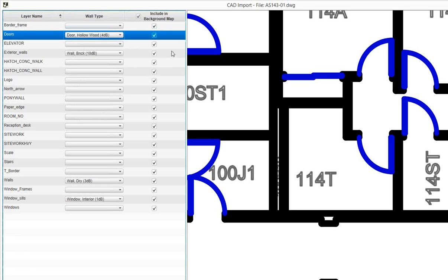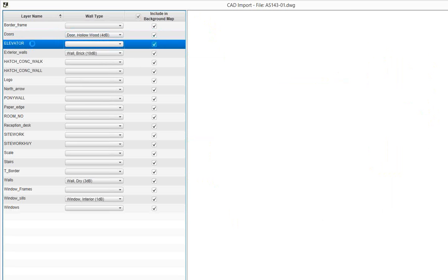I might as well actually close it for simulation purposes. Because how you want to do a Wi-Fi design is you need to have a scenario where all the doors are actually closed to make it the RF worst case scenario to create the maximum amount of attenuation. So ESS automatically detects the doors and closes them for you. All you need to do is assign the material.